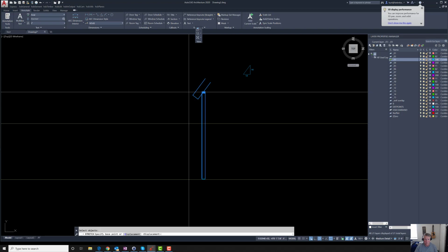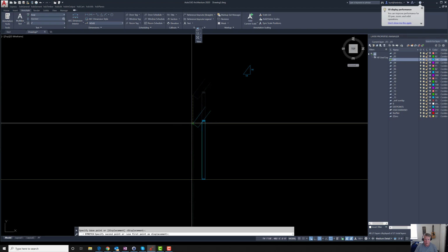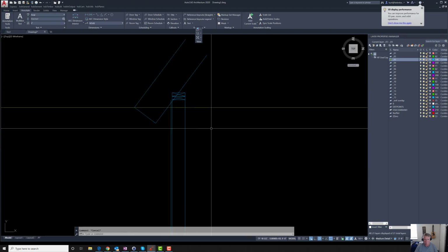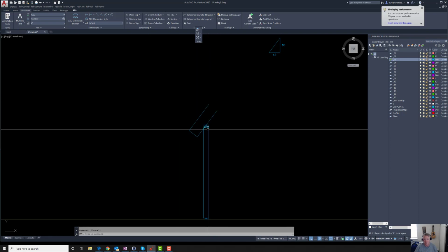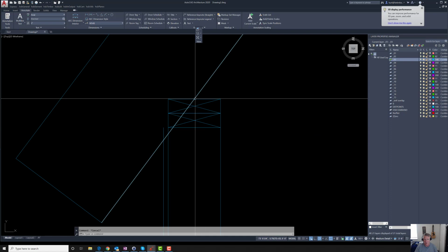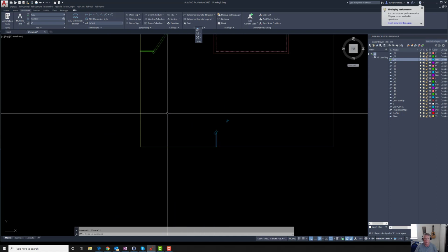And so now I've got that line running through the corner of my fascia, and I can stretch my entire wall to the right height for that. Now I can take a quick look at how that works for 8 foot 0 3/4. I assumed a middle bearing sort of seat cut here because this is the way I like to start things.